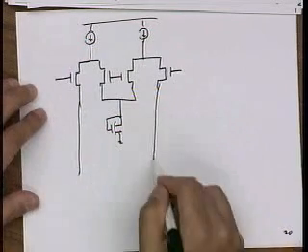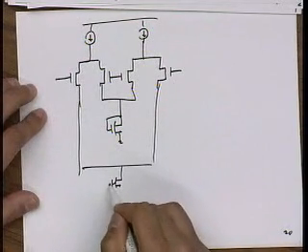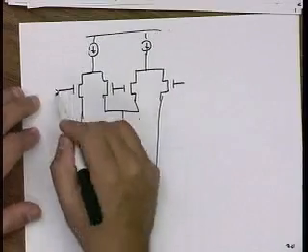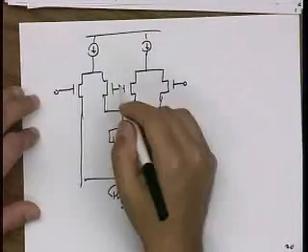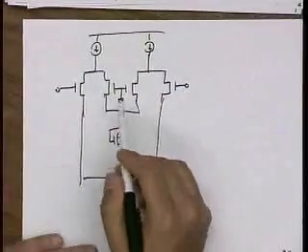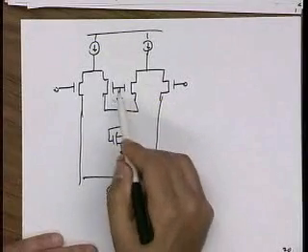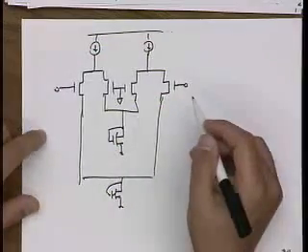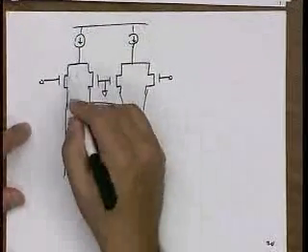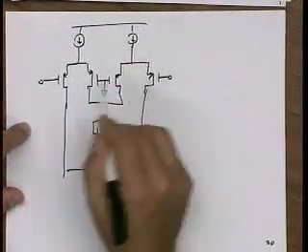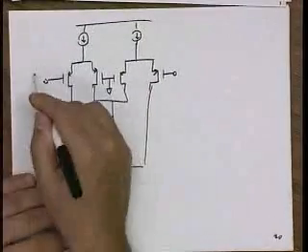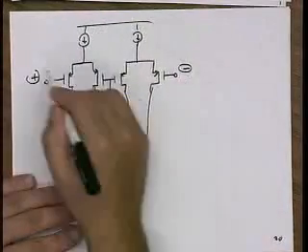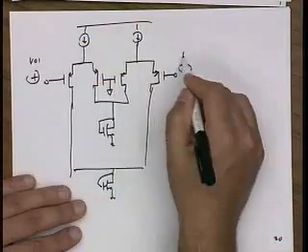So this is an all transistor common mode sense circuit. And so at the middle here I put in the desired common mode. Let's say it's 0, just for argument's sake. The observation is that, so these are PMOS diff pairs, and I tie my plus input and my minus input, so this is VO1, this is VO2.